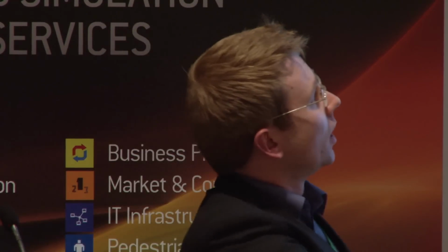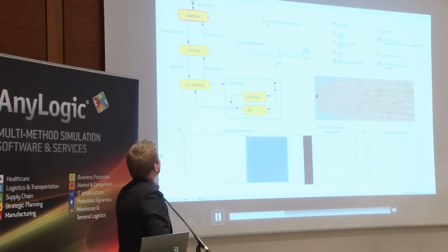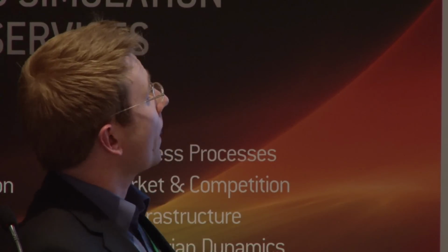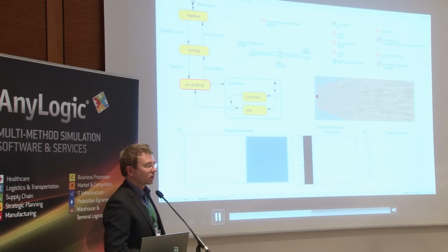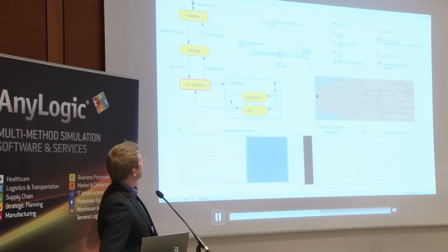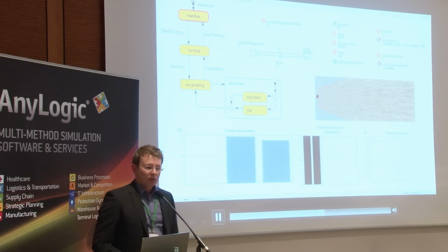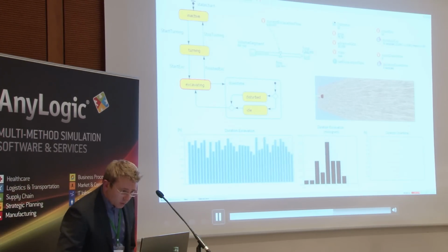You have a certain excavation rate, which results from the speed and the diameter and the swelling factor of the soil as well. Then ring build starts. You don't see anything here anymore. Then after ring build, this will trigger again the process of excavating. Then the system dynamics starts again when this is finished, and so I think you get the idea. I'm going to be fast forwarding this, I hope.